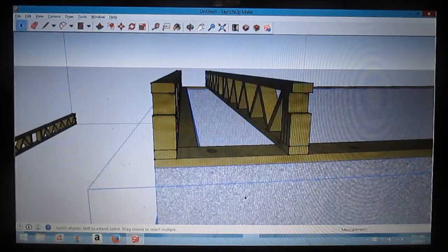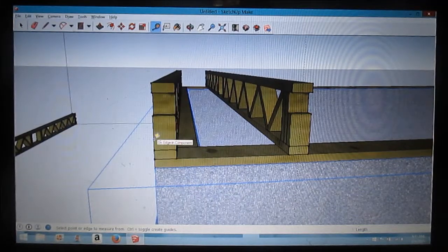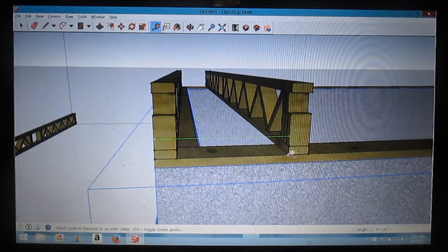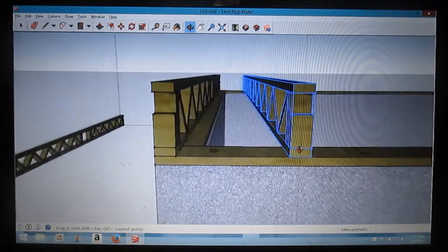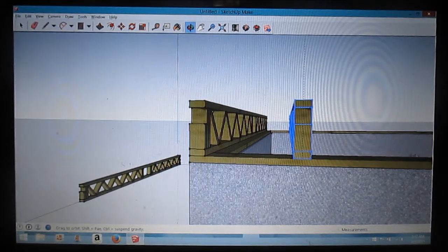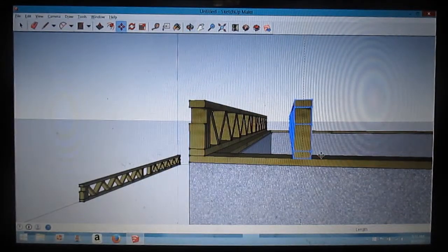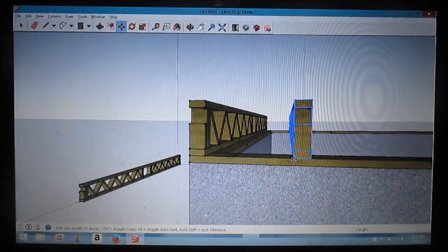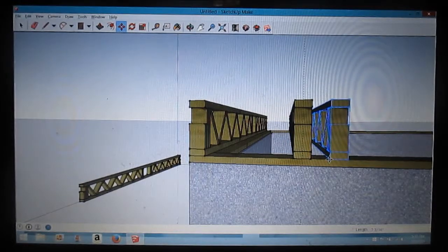Okay. Now I'm going to make sure I'm 24 inches on center. I'm going to click that and measure, which I am, 2 foot on center. Now I'm going to select this one, hit the O for orbit. Now from here on out, I want all my trusses to be 2 foot on center. So watch this. I'm just going to copy all this, and I'm going to hit the M button, select that, hit control. I'm just going to move it a little bit. Now I'm going to type in 24. I want it to go 24 inches.